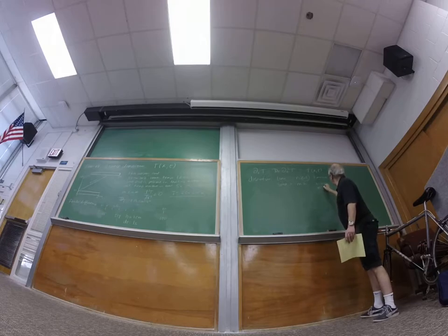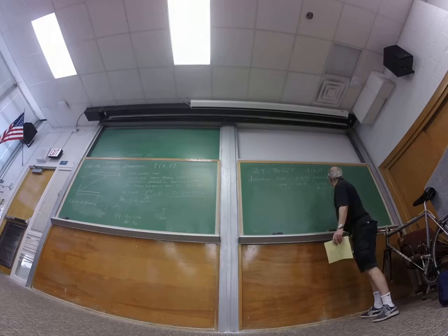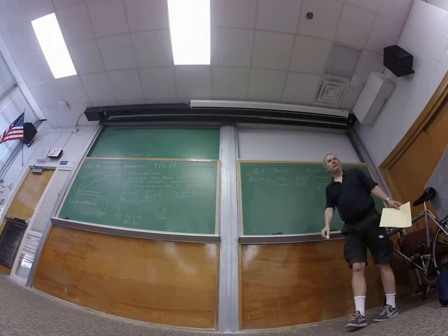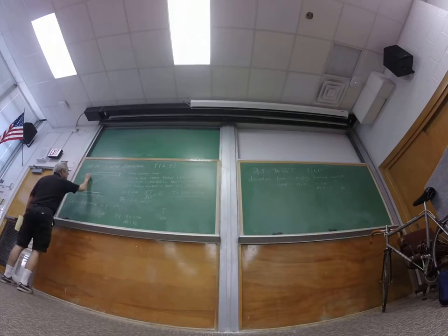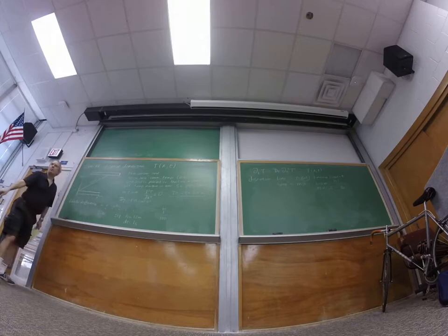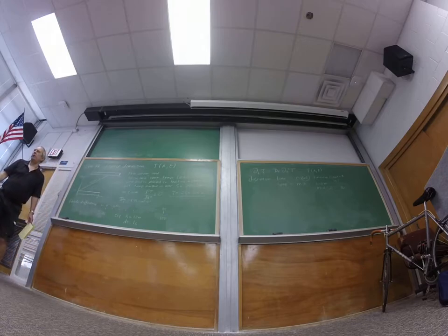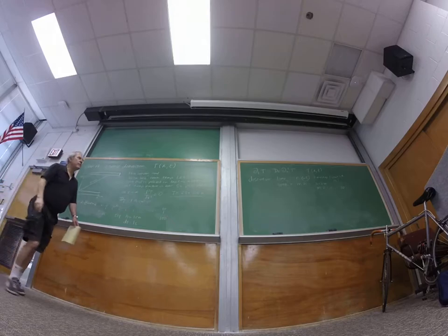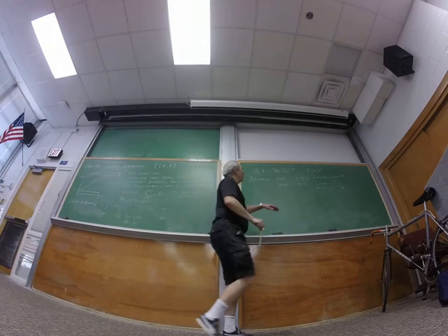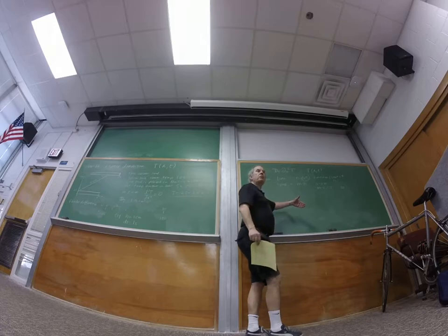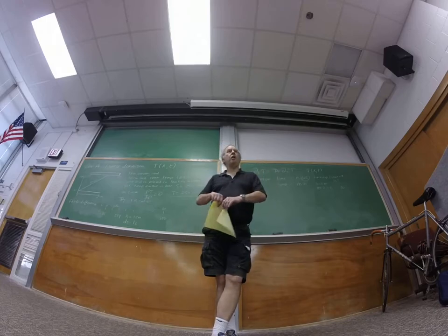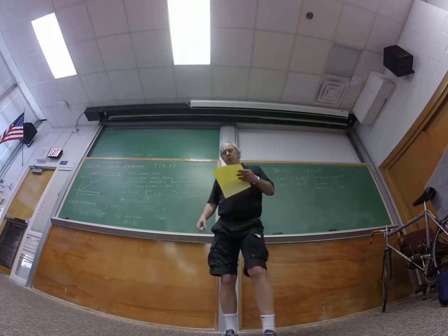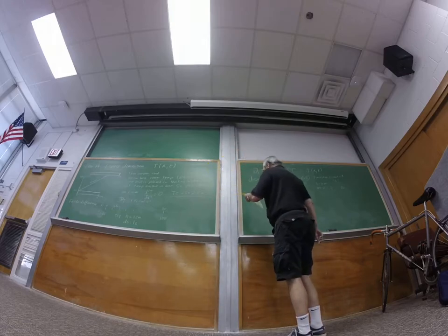So m will be 0, 1, 2, up to 30. Okay? So I'm going to calculate my temperature at those discrete times at each of those discrete points. Okay? And then what I'm hoping is that I then have enough information from this to be able to reconstruct and make a reasonable plot of the temperature field. We won't know that until we've actually solved the problem, so we have to essentially try and see what's happening and then maybe go back if it's not quite what we wanted.